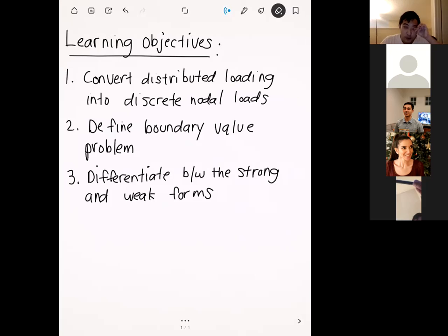After we finish the beam notes, the next thing is going over strong and weak forms. Judging by a lot of the feedback I've gotten so far on the truss and beam equations, and because I know a lot of you have done these kinds of problems before in statics, I'm going to skip lecture note 05, which had to do with frame equations, where frames are basically trusses and beams combined. It's everything we've been doing up to this point, but on steroids. Even problems that look relatively simple end up with a 15 by 15 global stiffness matrix, which is not fun to work with.